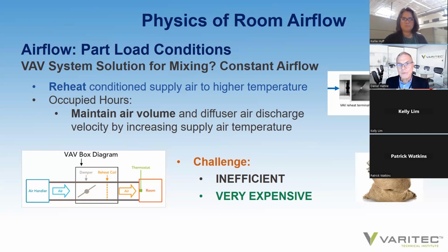We saw that with variable refrigerant flow and evaluating electrical loads from 115 volt DX, cheap, lowest first cost, versus 480 volt, 3-phase variable refrigerant. We saw a significant reduction in the electrical load that begged the question of whether VRV was actually a cheaper first cost solution for the owner because the electrical component was taken into account.